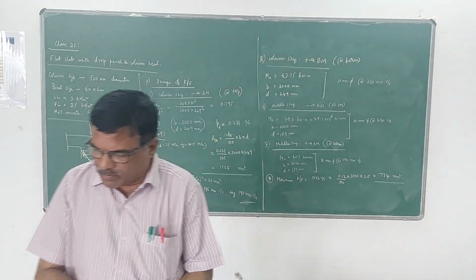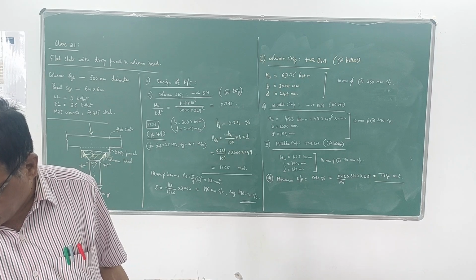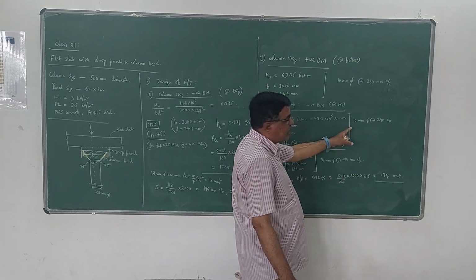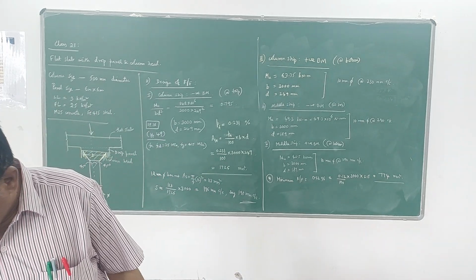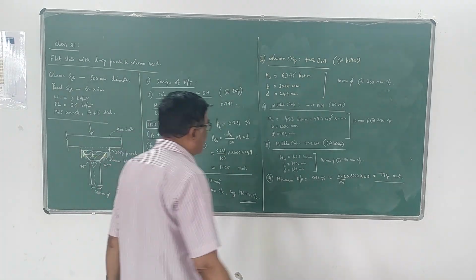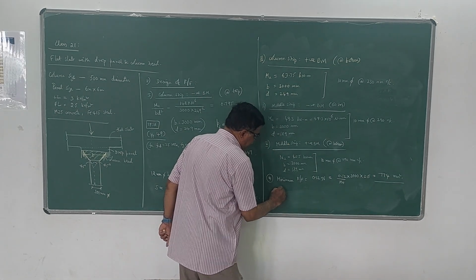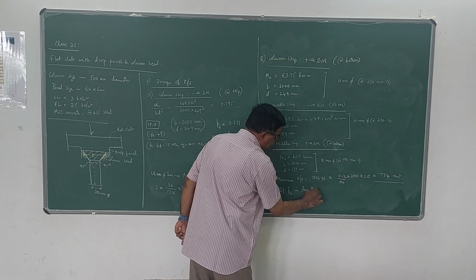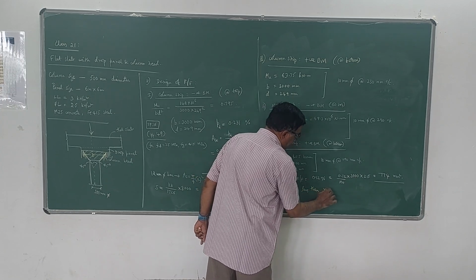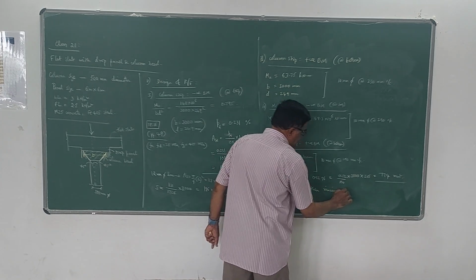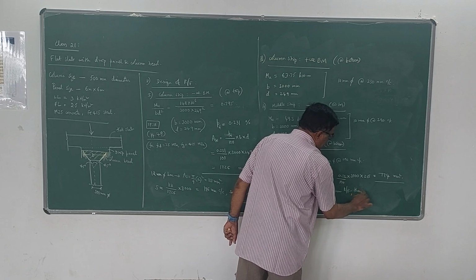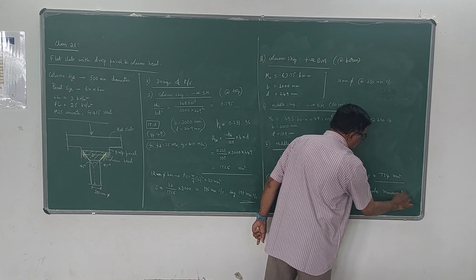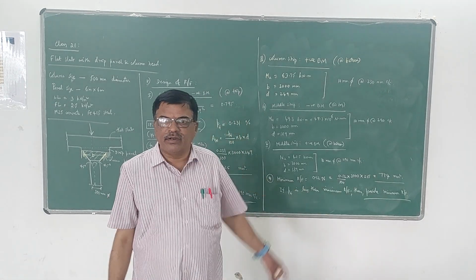Actually, what happens here in the third and fourth cases, in the last case, you are getting less than 774. That means, in other words, if PT is less than minimum reinforcement, then provide minimum reinforcement. Correct? That's right. You have to provide minimum reinforcement.